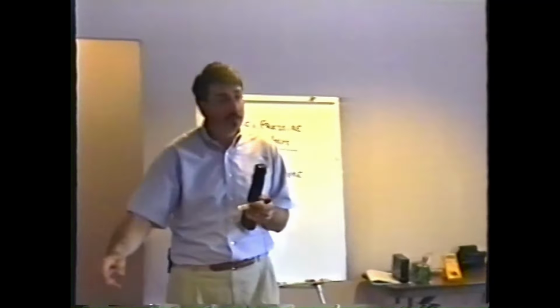Earth ground. Well, you know how in most vehicles you have a 12-volt car battery, and you know how the negative side of the car battery is connected right to the chassis of the car? It's called negative ground. If you lift the hood of any car and look at the car battery, the negative side of the car battery will be connected through a real thick wire, and it'll go right to like the engine block or the chassis or something like that. It's what they call a negative ground system.